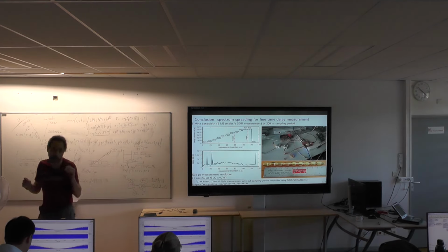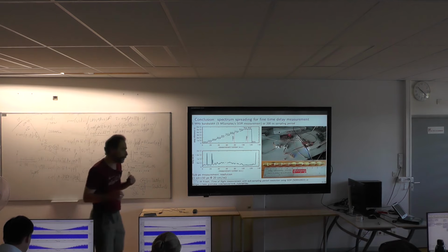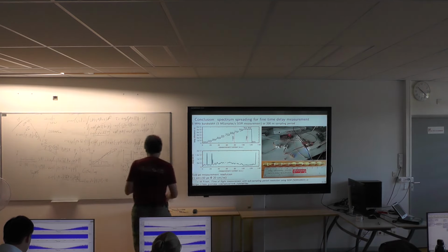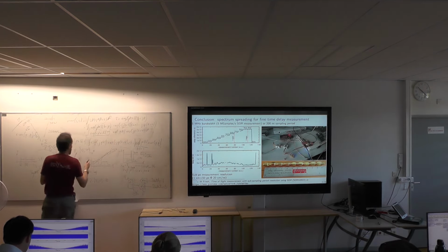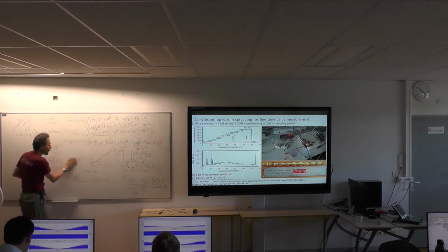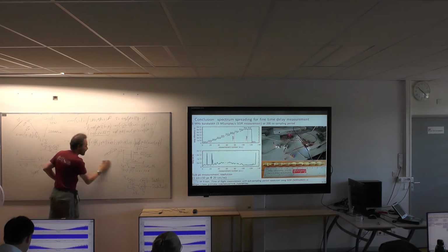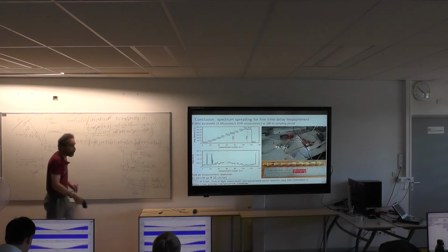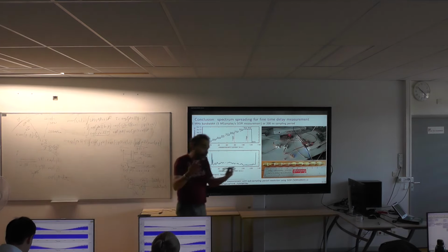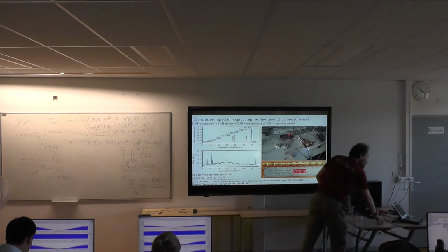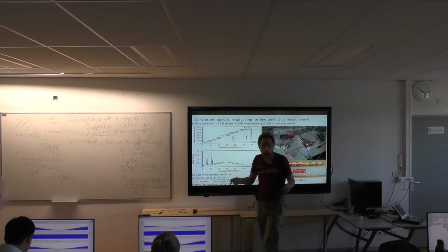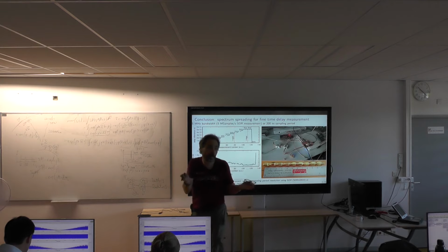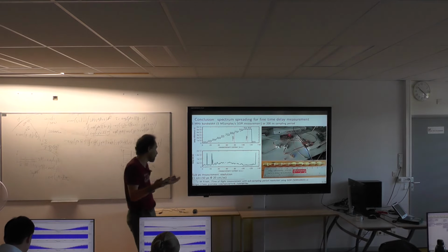One thing I find amazing with correlation, and it was hinted at if you attended yesterday's lecture about power grid surveillance: you sample at a given sampling rate, so you might think the resolution of the time delay of my correlation peak is determined by the sampling rate. If I want 1 nanosecond, I need 1 gigahertz.